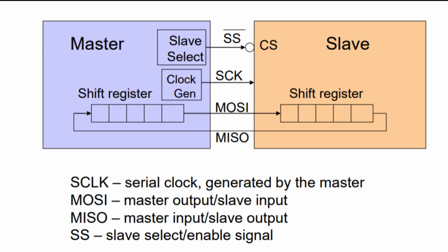Basically, yes. Method 2 is a fixed processing delay. The master just waits. It sends a command to start a measurement, then simply delays for a known amount of time based on the slave's datasheet specification for how long that operation should take. After the delay, it assumes the data is ready and reads it. Seems simple, but maybe risky. It is simple, but risky. If the slave's processing time isn't strictly deterministic, maybe it varies with temperature or workload, the master might read too early and get old or invalid data. It's only suitable if the timing is very well defined and consistent.